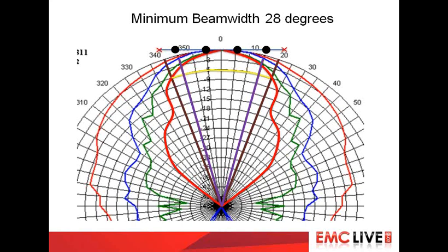So now, we've actually gained quite a lot of information here. We've got a large don't care area. If it falls outside this slice of cake defined by the two brown lines, we really don't care. And we've defined a keep out area, where no matter how hard we try, if there's more than 6 dB difference between what's at the boresight there and what would turn up at those two red crosses, we've lost already. There's no way we can fall within the limits defined by the standard. And this is quite useful information when you're designing, because people are quick to blame things on room effects and so forth, and you are in fact allowed to drop 4 of those calibration points, allowed by the standard to do that. But where I'm going here is, in basic theory, it cannot be achieved. When you put it in that chamber, it can only be worse. It cannot get better. You're on a hiding to nothing. You can't win.